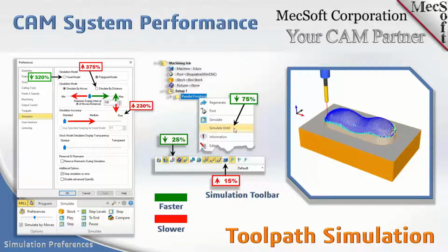Okay, so the denser or tighter the spacing, the more accurate your representation. One other note: these settings are not going to affect your toolpath at all. The toolpath is already done; we're just using this for simulation. It'll affect the quality of the simulation display on your screen, but your toolpath quality stays exactly the same.